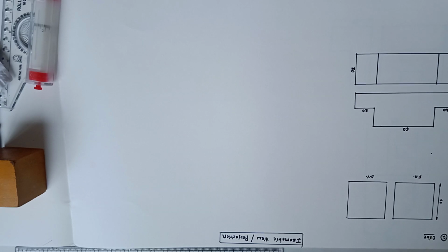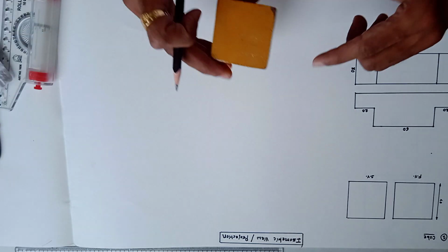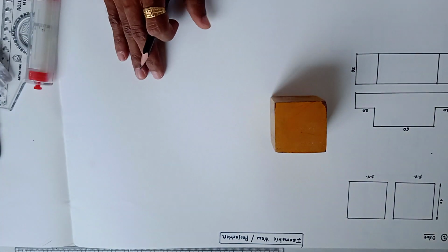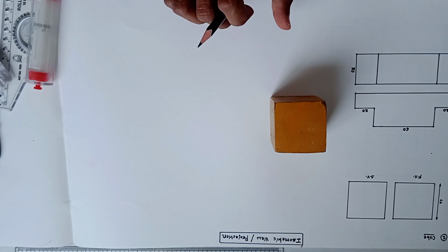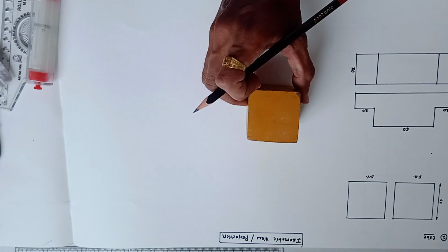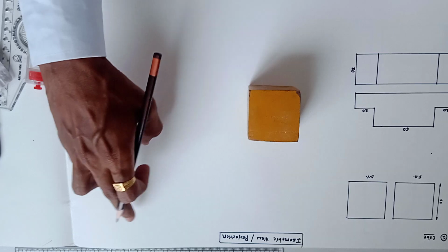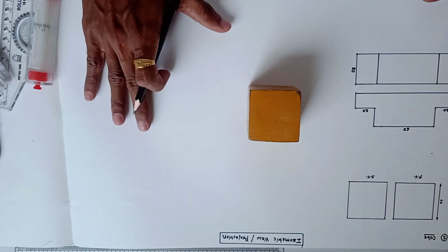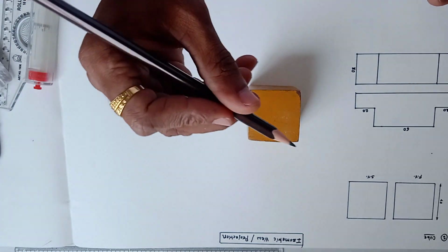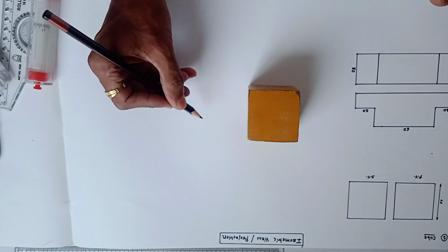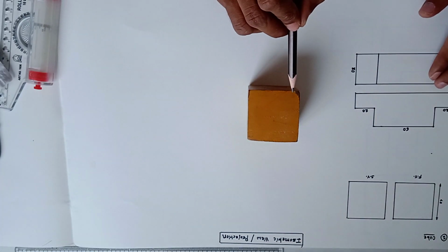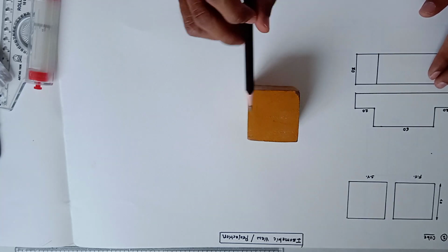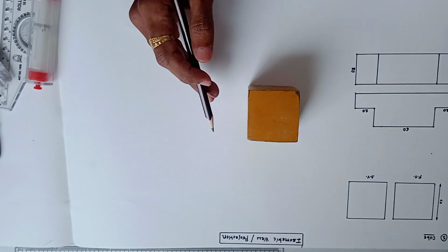If you refer to the orthographic projection, we observe in the direction perpendicular to the vertical plane or horizontal plane. Take the simple example of a cube. Here I have taken the cube. There is a vertical plane, which is the drawing paper behind the cube, and if you observe in this direction, perpendicular to the plane, then we can see only this square, which is the front view. So this square is the two-dimensional view of this object.